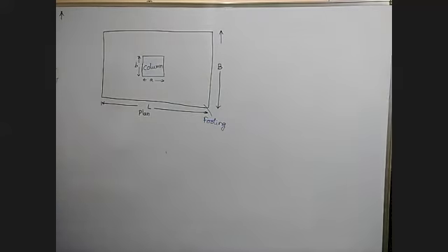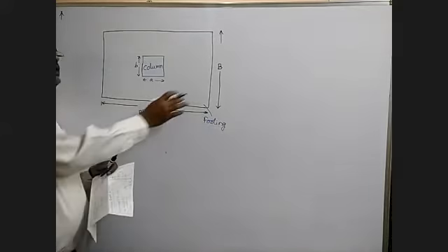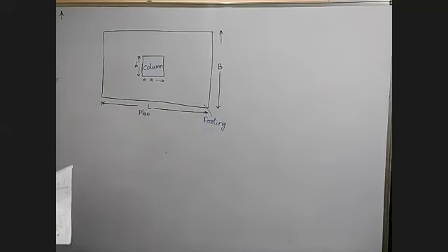So from the area of the footing, area is the load by SBC, the soil bearing capacity. Load divided by soil pressure is the area. We calculate L and B if it is a rectangular one. If square, then take the square root.